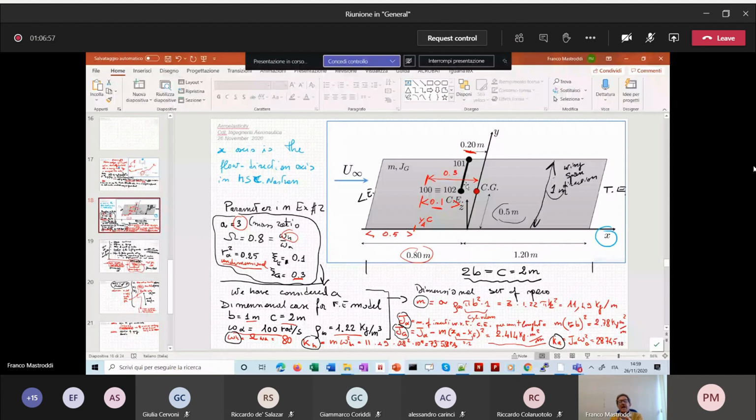It's just to allow to implement an interpolation strategy between the structural degree of freedom, which are the degree of freedom of such nodes, and the aerodynamic degree of freedom, which are associated with the unique lifting surface we are defining. Okay, so from a physical point of view, the definition of this rigid stick does not make sense, but is useful only for the numerics.